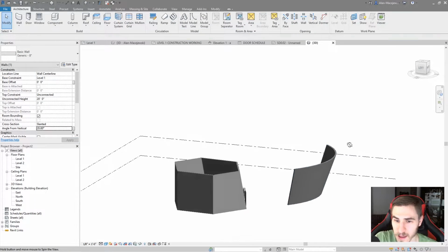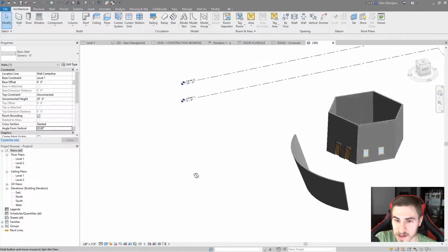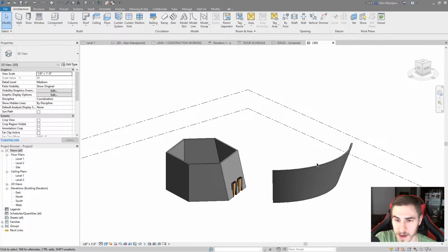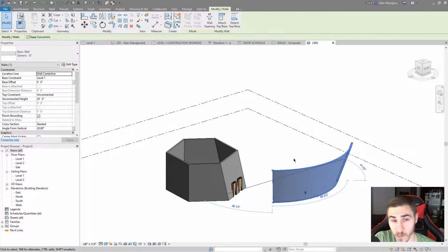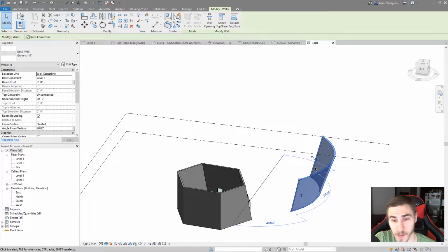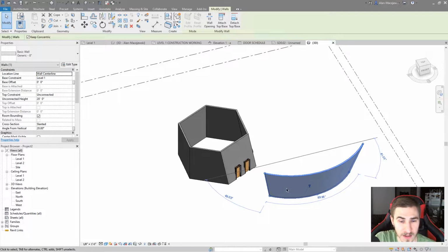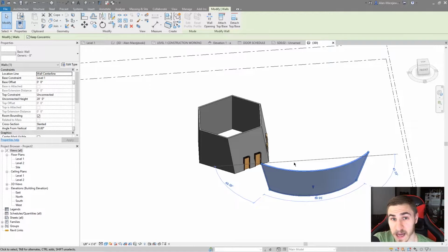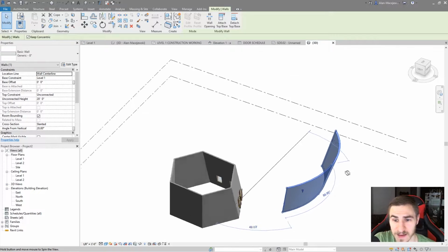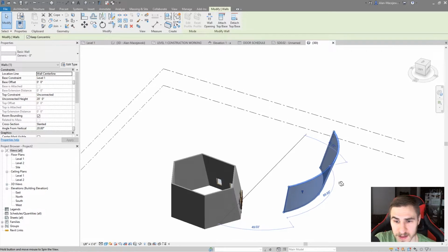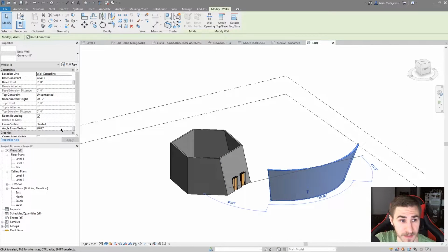And it would take so long to get this kind of an angled wall, especially a curved wall in Revit. You'd have to use a mask, you have to extrude the profile. It was just a mess. But the fact that you can do this so quickly is awesome. I can see myself just throwing lots of masks together and doing studies in Revit, and I get to actually use walls this time instead of masses. I never really enjoyed working with masses, but now that this works, it's awesome.